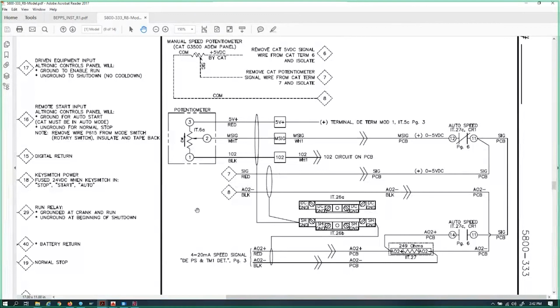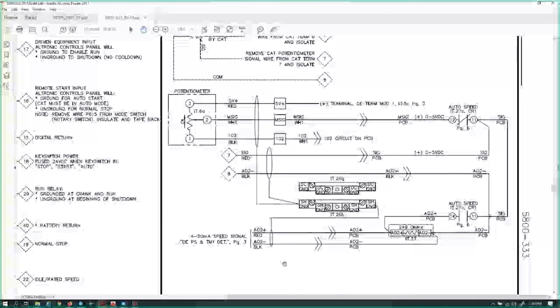I look at the electronic panels as kind of the way we follow our schematics is more of a ladder logic / point-to-point hybrid system. To me, I can follow the ladder logic and they tell the story, but they also tell exactly where each wire goes. So personally for me, it's one of the easier schematics to follow in the industry. And I've been challenged by a few people, but that's just because they learned on another system.